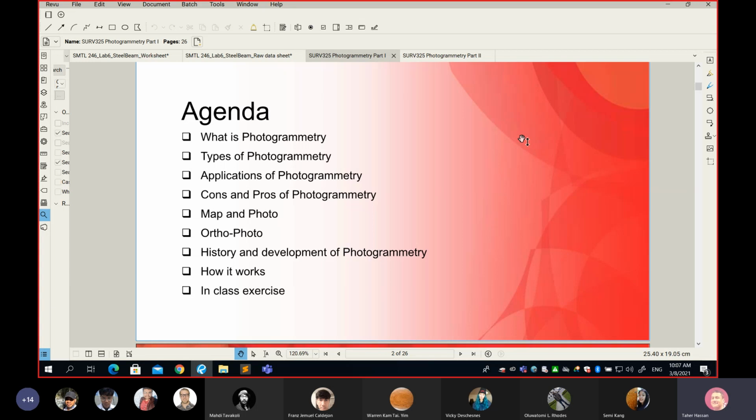So that's why the rule is, in photogrammetry, we must have at least two photos covering the same area. And this means my photos must overlap. If the photos overlap, then we can locate a point in space by something called forward intersection. So we create kind of three-dimensional lines, and those lines simply locate the point in space.